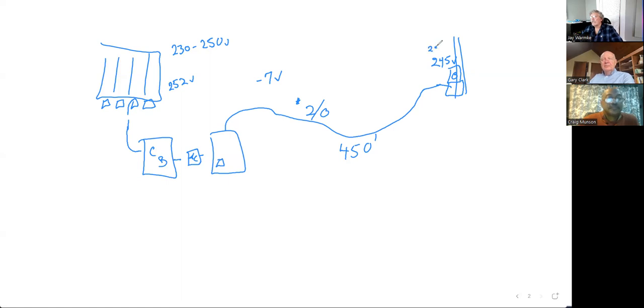So I think the voltage might have been around 250 volts, because when they generate the voltage at a substation, they set it high, because by the time it gets to the very end of the line, they've lost power too. And they've got to have at least 240 volts at that last site. So the closer you are to the substation, the higher your voltage is going to be.